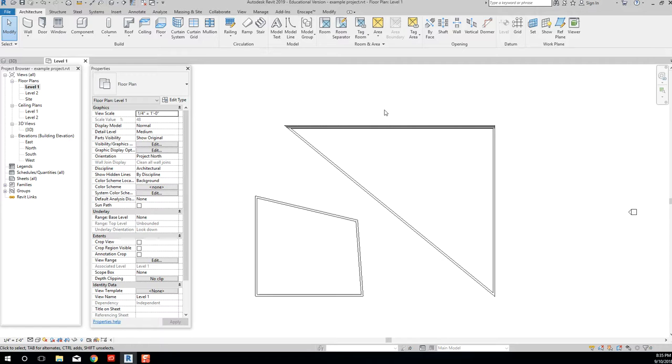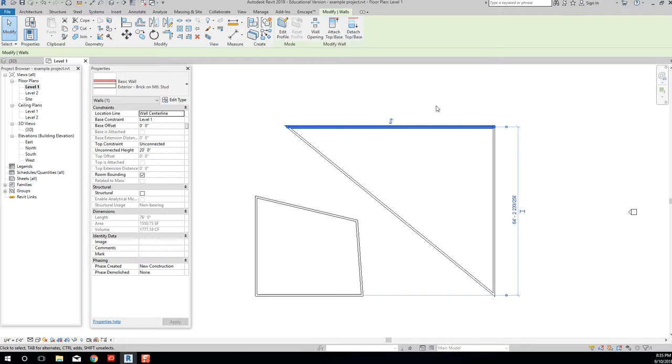The first selection method we have is the pick. So I'm going to hover over an object, click, and I picked the object. The pick is essentially a one-by-one selection method. So I can pick, and I'm picking individual items, right, all in succession. Now, here's going to be something that's a little different from AutoCAD, right? If I click on this object, I pick it, and then I click and pick, that first object deselects, okay? So here's a really kind of weird workflow when you're going back and forth between AutoCAD and Revit, right?